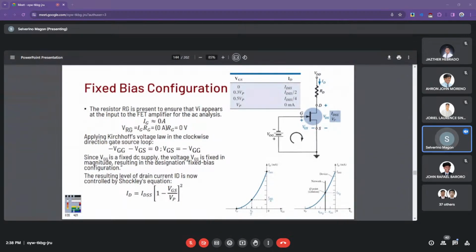So some common analysis includes the half current, well, not really half power point, but half of the current span of the saturation, the quarter, and the case where you have a zero drain current. In most cases, this translates to: if you have drain to source saturation current, you have zero VGS, or zero voltage applied at the gate to source.